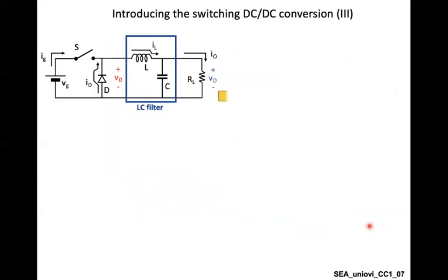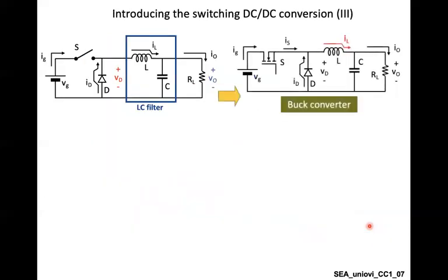So in order to understand the process, we first consider what's called a buck converter. It's called a buck converter because, as we will see later on, my dear students, this converter acts to buck or reduce the voltage, so the output will be lower than the input, or VG here. Let's see how this will happen.